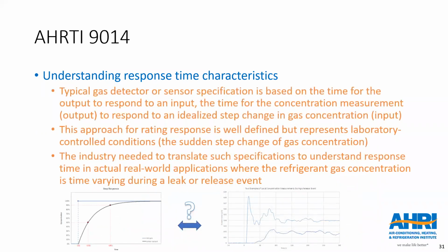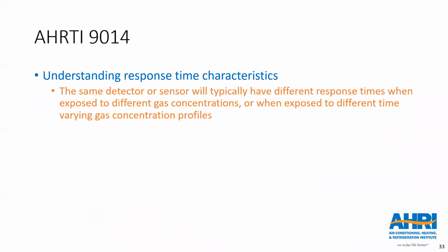And next again. So the refrigeration, air conditioning, and heat pump industry needed to know how to translate the response time ratings, T50 and T90, into practical terms and assess what would happen during actual leak or release events. Another issue is that the refrigerant detection system with a fixed set point will typically have different response times when exposed to different gas concentrations. So let's take a look at some examples to explain what I mean.